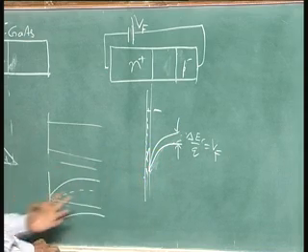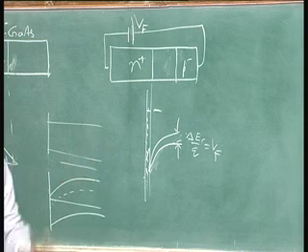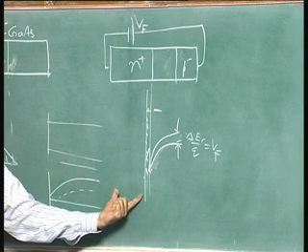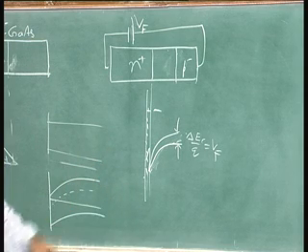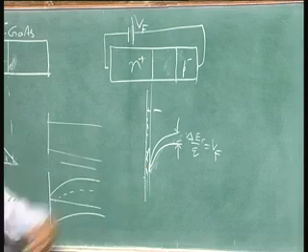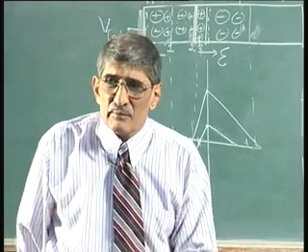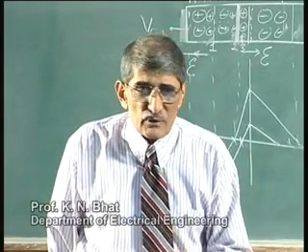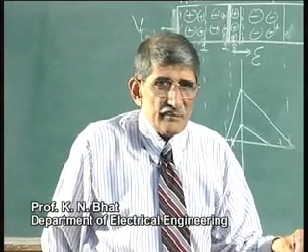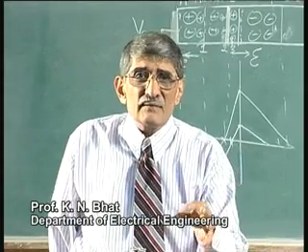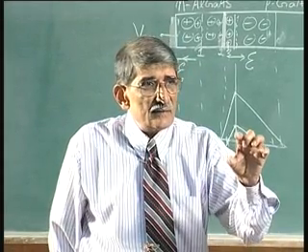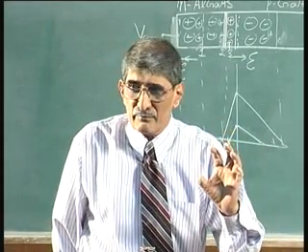So, what we are saying is, if you apply a voltage equal to delta E c by q across the junction, you will be able to reduce the charge practically to 0. Because in the homojunction, when V BI is V T log of N D N A by n i squared, the charge there is minimum, but that extra charge is present at the notch corresponding to the delta E c by q potential change.